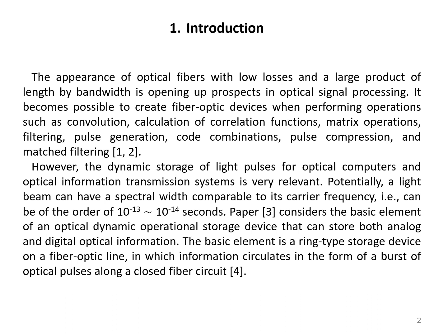The appearance of optical fibers with low losses and a large product of length by bandwidth is opening up prospects in optical signal processing. It becomes possible to create fiber optic devices when performing operations such as convolution, calculation of correlation functions, matrix operations, filtering, pulse generation, code combinations, pulse compression, and matched filtering.